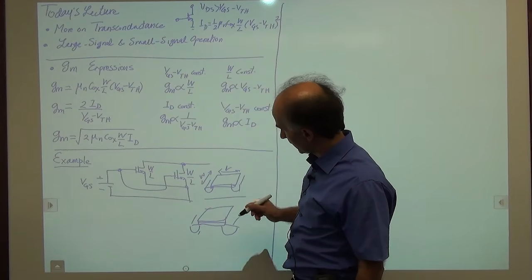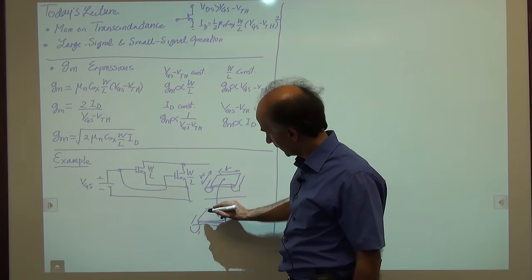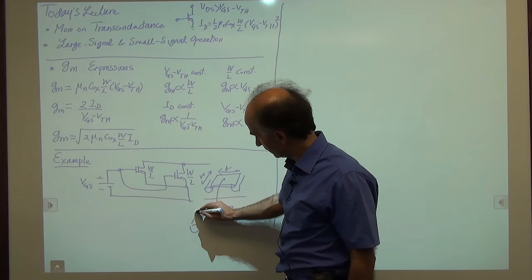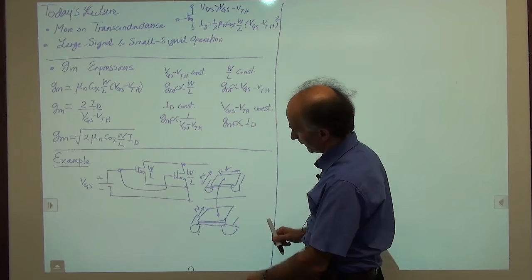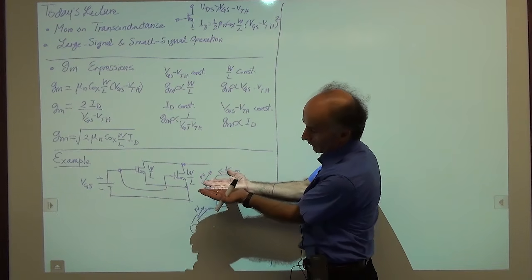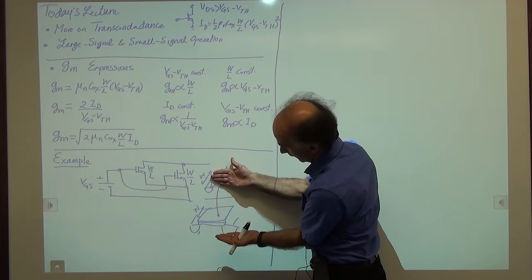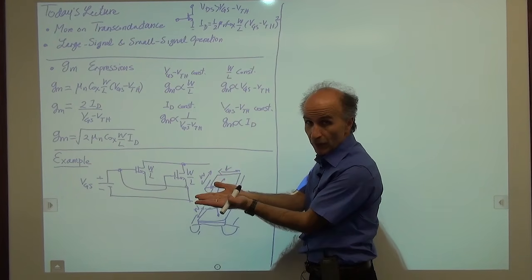So now what happens is, when these two gates are connected to each other, and this is also W, we see that it is as if the two devices are connected like so, as if the width of the device has doubled. Okay, imagine you just take this and place them next to each other.